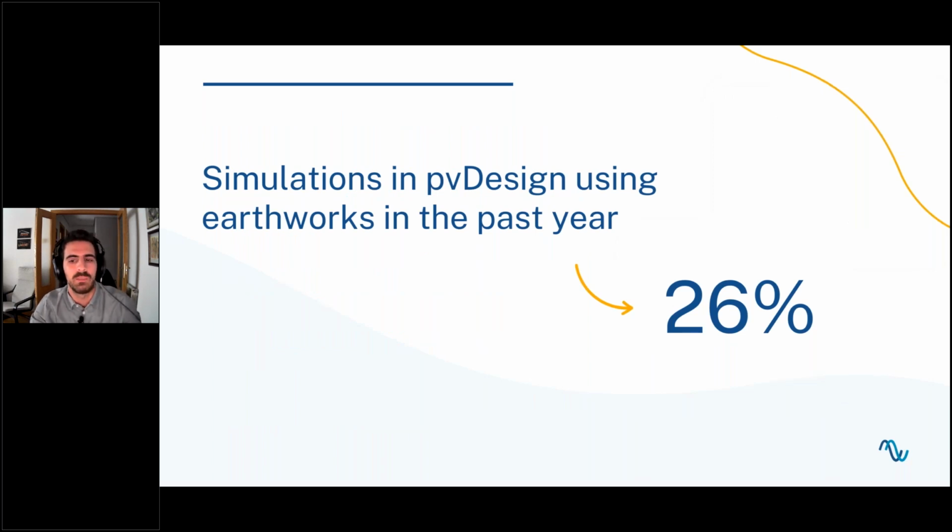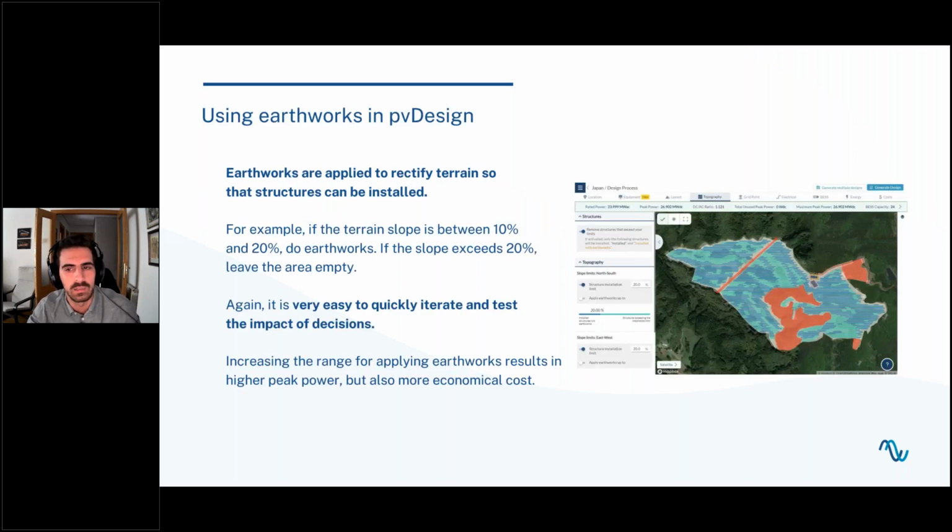Nowadays, 26% of pvDesign simulations are using earthworks, which again, is a very significant proportion. And it's very easy to use. You use it in the same design process tab as the regular topography filters, and you specify the slope range where you would like to apply earthworks.